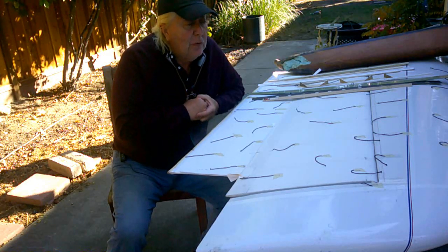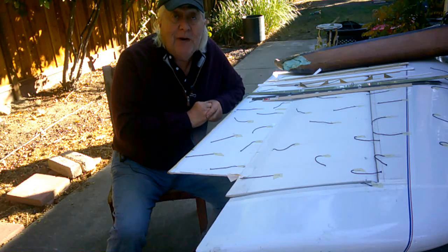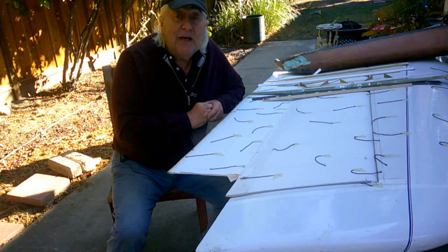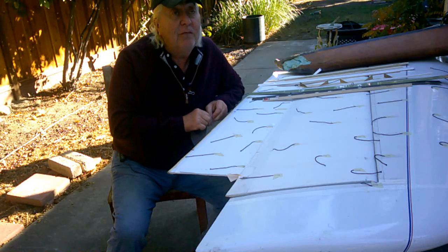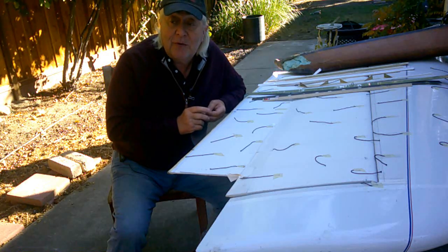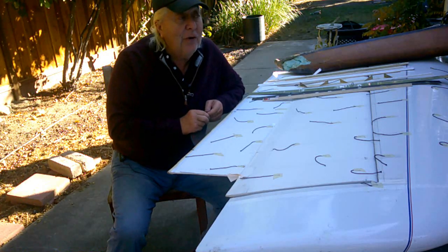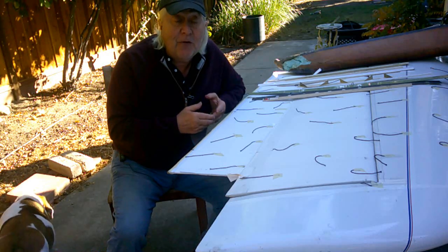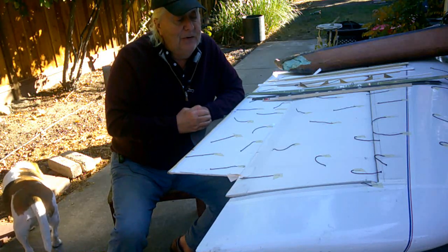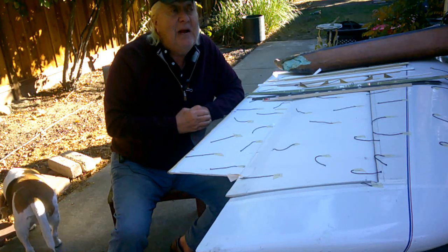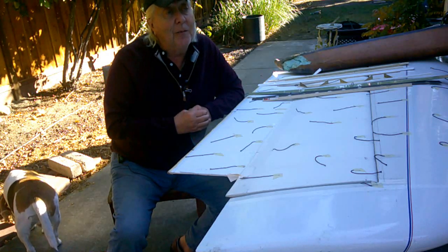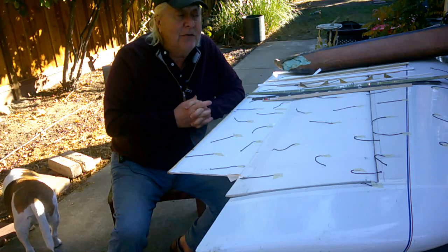So, why are you so wrapped around this whole Reynolds number issue? Well, I think it's indicative of what's causing the problem on my wing. It's not that low Reynolds number causes a problem. The low Reynolds number just tells us something about the flow conditions that are causing the problem. So it's a measure that we can look at. It's a non-dimensional measure we can look at to say, oh, am I in a problem region? Am I in a good region?